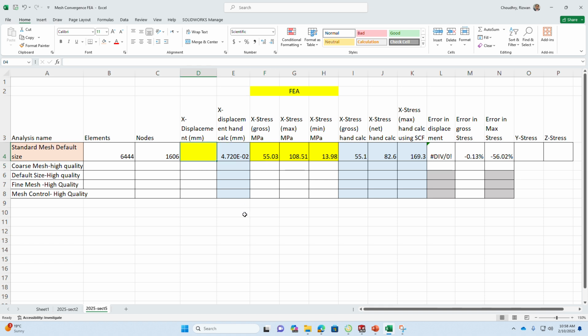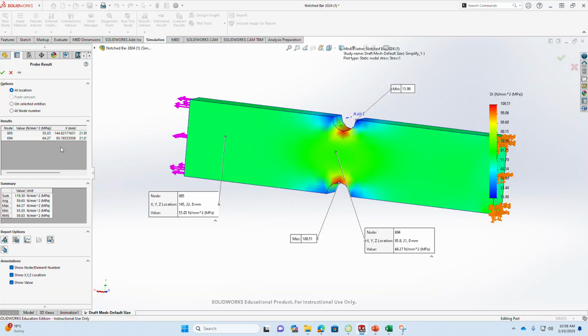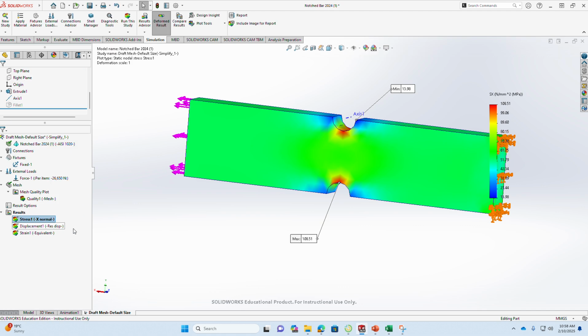Then we can also compare the displacement along the x-axis. So to get some idea about whether this error is because of incorrectly setting up the model, or because of a genuine effect that we cannot account for in our calculations, we can go back and check our displacements. So displacement wise, you should see less error, because the displacement, as I indicated to you, is cumulative.